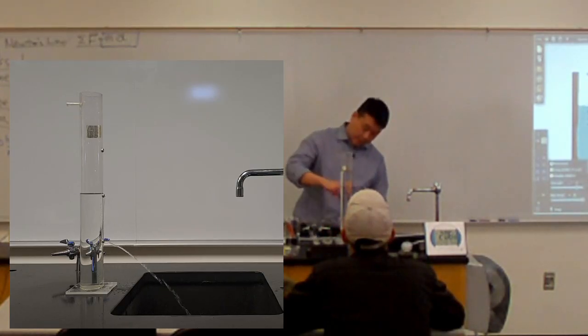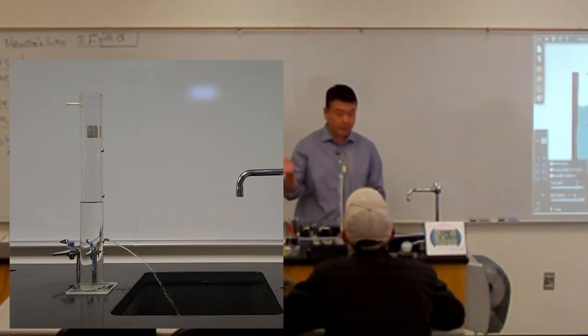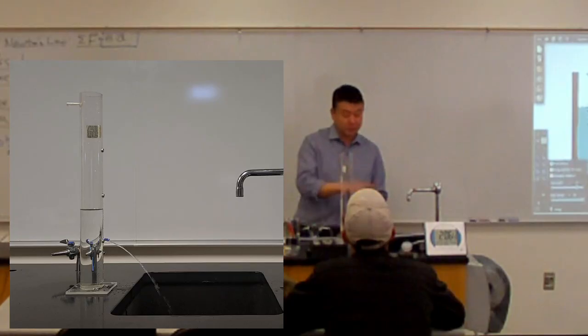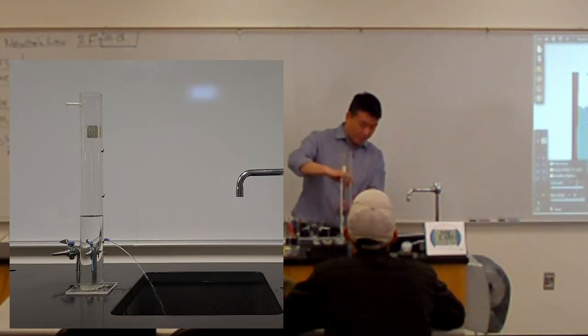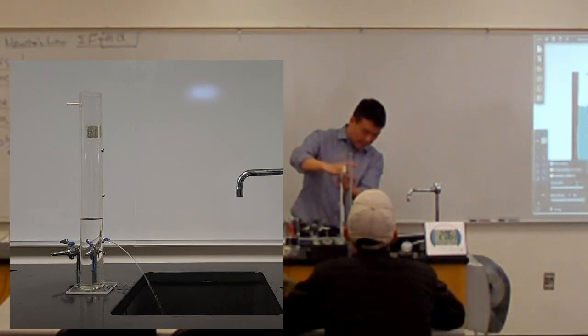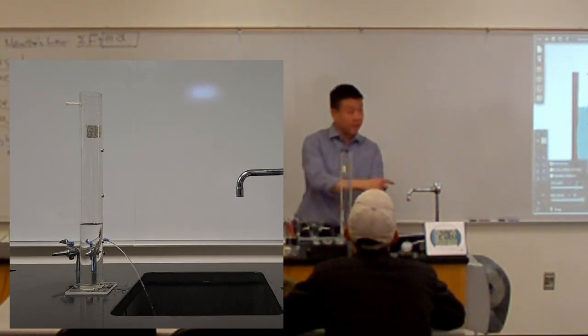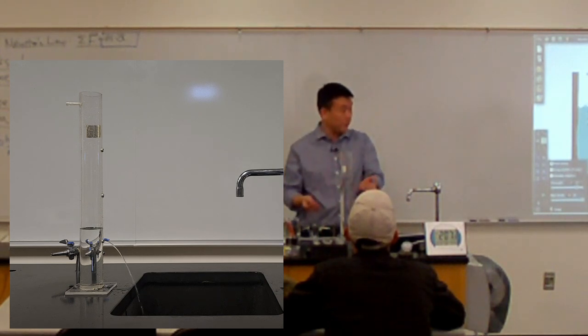And in fact, when the water comes down to exactly this height, no water is getting pushed out. I mean, at some point it's because water is below, so there's no water to get pushed out. But as it's approaching that, when you barely have just a little amount of water, water basically leaks out. It's no longer shooting out. It's because at this point, there's really no pressure here at all.